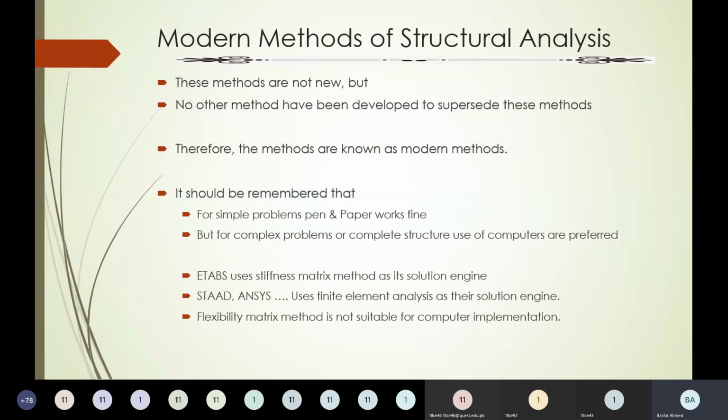But the point is, do we know each and everything of the software, how it is working? Probably we make a mistake in the input data. Probably we make a mistake in setting up the parameters, which will definitely result in a wrong solution. So expertise is always required, and other than that, a random check is also required.